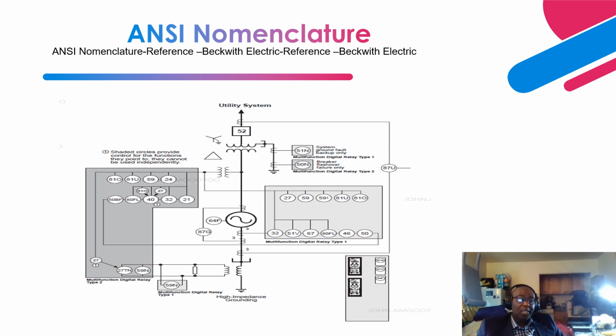For the protection scheme of this generator step-up transformer, as you can see over here, we have a 51N element and a 50N. This one is an instantaneous neutral overcurrent protection, and this one is a time neutral overcurrent. So this one acts instantaneously, and this one operates based on an inverse curve. All these protection relays can be a multifunction digital relay, a microprocessor relay. So you can have all these protective elements in a single relay.